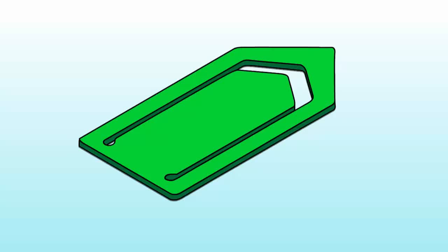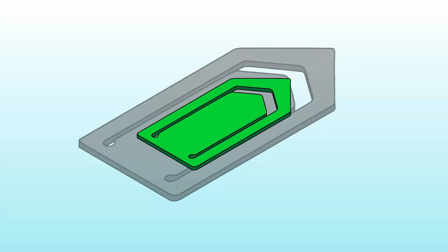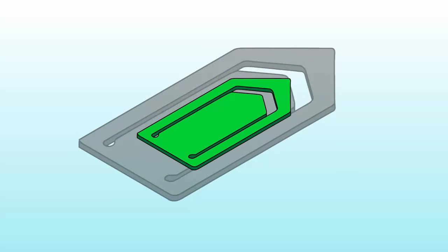Shrinkage is a change in size. It is a characteristic of all plastics and occurs when plastics cool from liquid to solid. All injection molding components are subject to shrinkage to varying degrees. It cannot be eliminated, but it can be minimized and controlled.